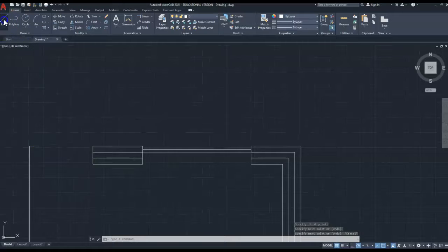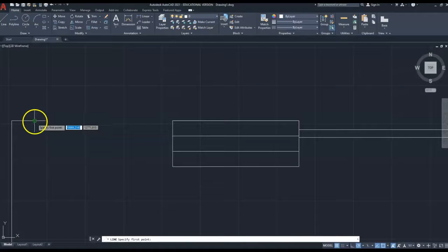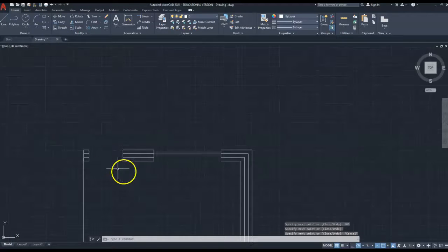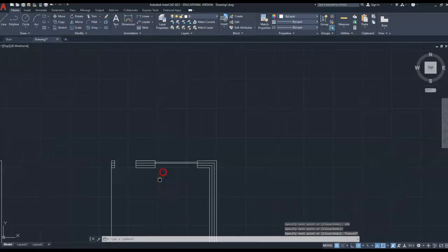And I'm going to do the same here. So we're just going to go 100mm, return into there, escape, and then I'm going to go back on to draw line. From that point to there, I'm going to go 300mm. I'm going to return into there. I'm going to go up there 100mm and back out. Click escape. So now you can see the cavity walls being formed.